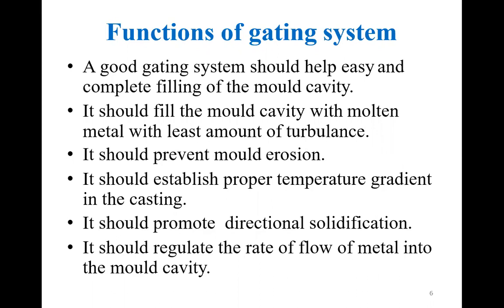So whatever temperature you maintain at the completion of your molten metal, it is better to maintain the same temperature, so that after it is carried over to the mold cavity, if the temperature decreases, it's okay, and we can reduce the defects also. It should promote directional solidification. You know what is meant by solidification, right? It should regulate the rate of flow of metal in the mold cavity, that is, from each and every ingate, how much quantity is flowing.